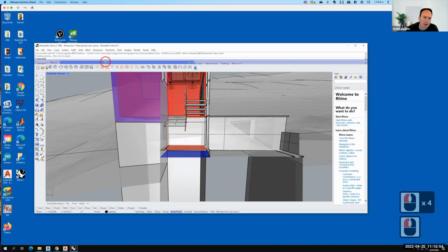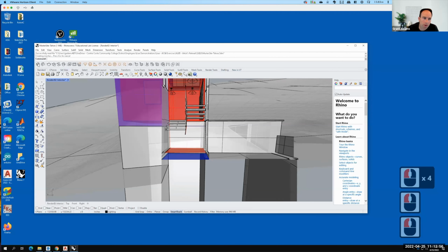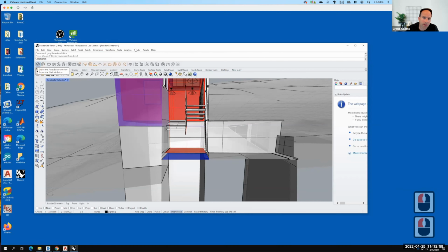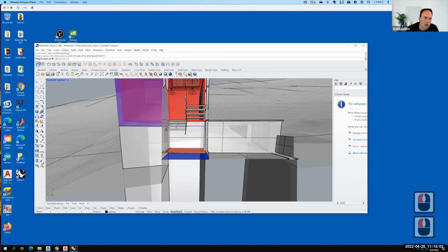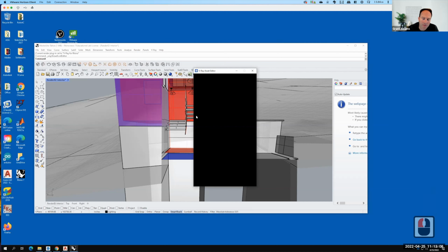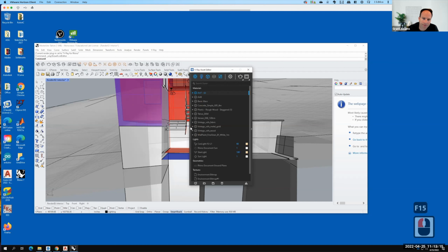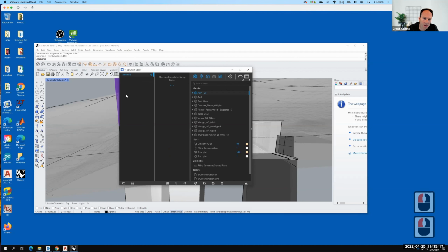When you first open up Rhino, open up the V-Ray asset editor. Oh, I have to change the default renderer here. Open up that asset editor and download all the materials that are missing, because that's going to plague you with problems down the road. Let's go ahead and download that, just so that they're local on the machine.